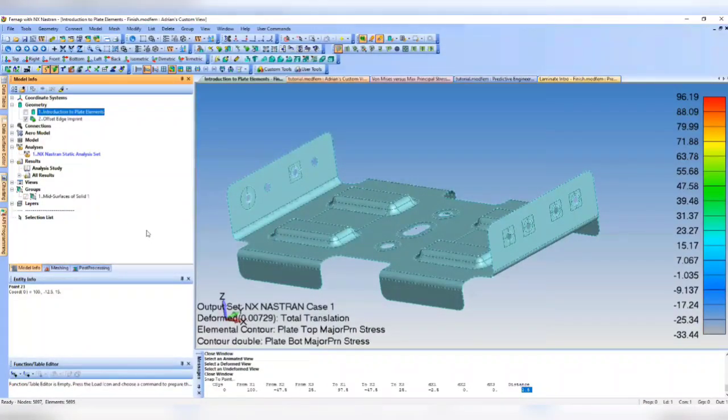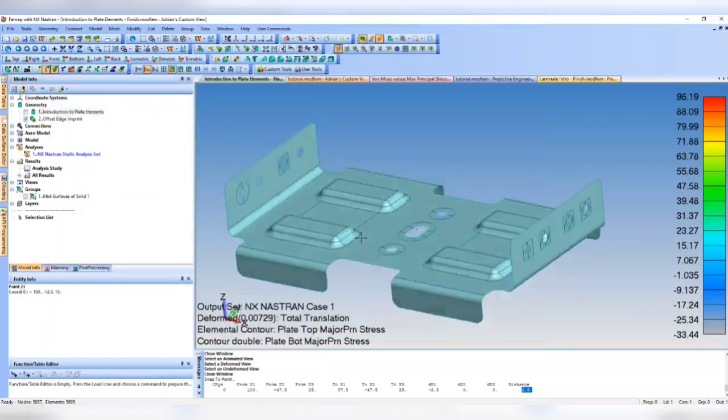When you're dealing with very large systems like an aircraft, you don't want to go all 3D, or else your model is going to be very bulky and very expensive. What I mean by expensive is the run times are going to be extremely long, much longer than shells. And you have to understand, we're not just running one load case. In the aircraft industry, we run thousands of load cases, thousands of different scenarios. So it's very important to have a very efficient model.